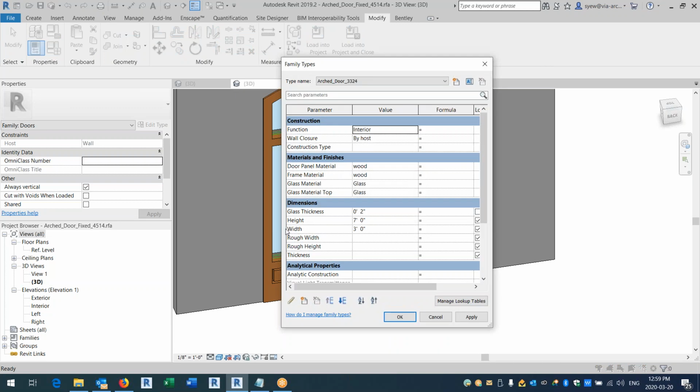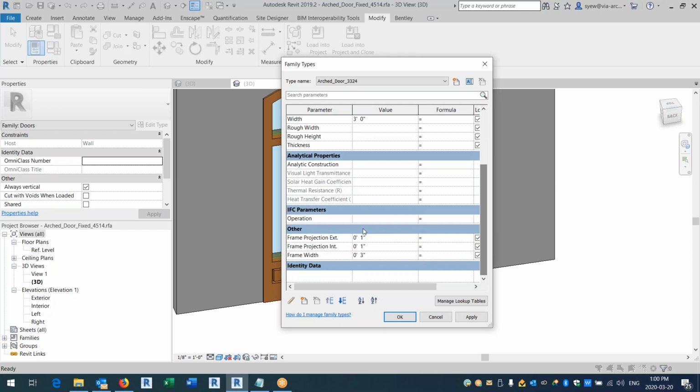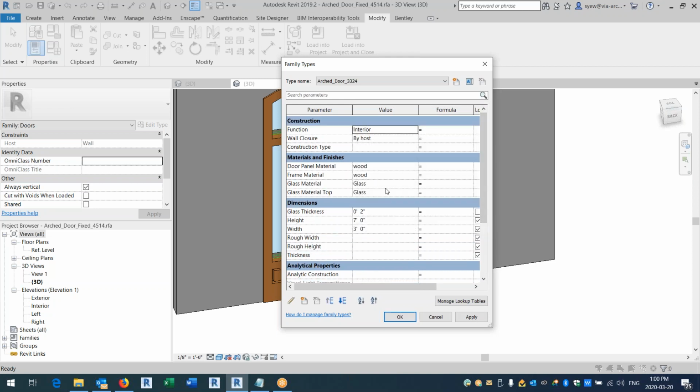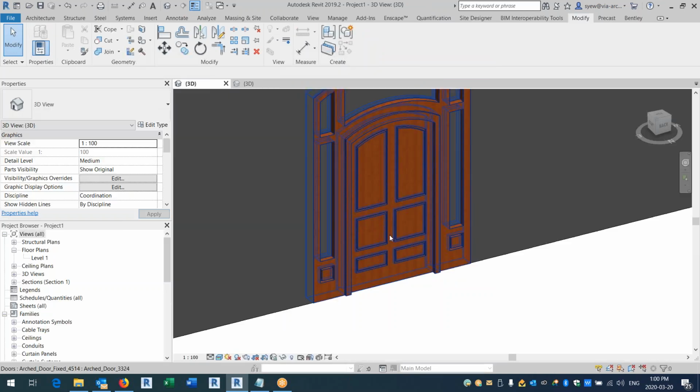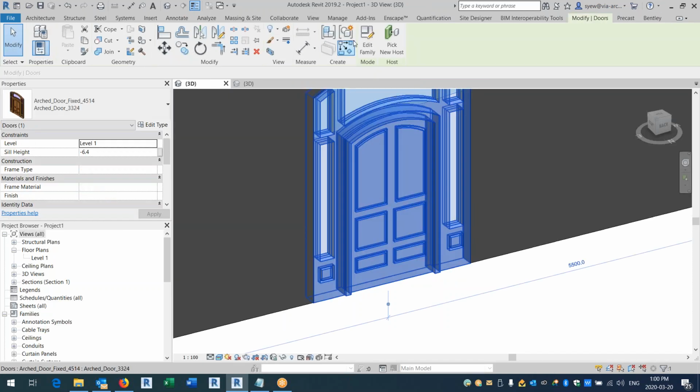The best thing I would do is that if you want to override a lot of the stuff, let's say the parameter changes and stuff like that, you will load it in. If you get that message, yes, you can override it, but sometimes you will not get that message. How I typically like to do this is that you can change a bunch of parameters. Let's say for this particular one, changing the material is a perfect example. Here, if I load it in again, you see that it will not give me the message.